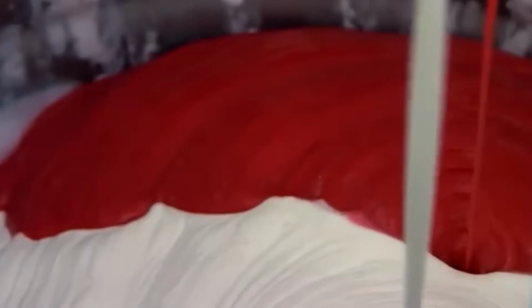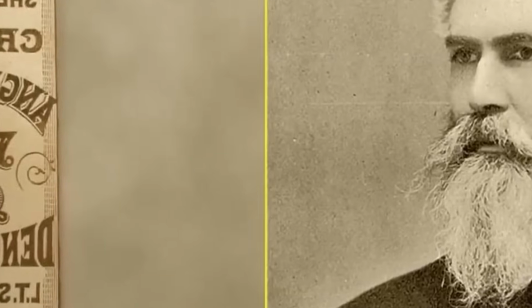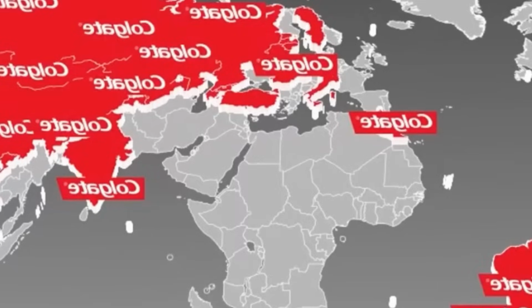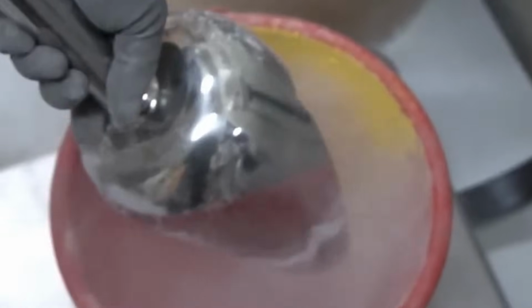For laminate or plastic tubes, the tail is heat sealed using conduction or impulse sealers. The sealing bars clamp the tube end, applying pressure and heat to fuse the inner layers. For aluminum tubes, the tail is folded and crimped mechanically by a multi-head crimping tool. A batch code and timestamp are embossed or inkjet printed onto the sealed end.